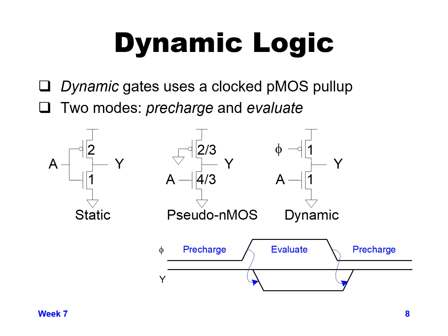So as shown in the bottom there, we have two modes. Pre-charge, when our clock is low, we're pre-charging the output value and it's always going to be high. And when the clock goes high, we can evaluate the value of A, which can either go to a 0 or 1. Depending on what it is, we'll get the inverted value out.